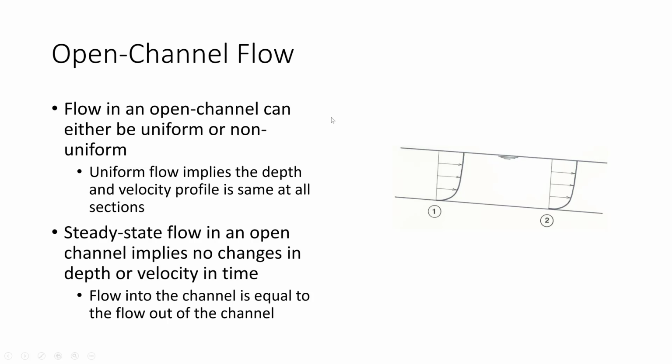Right. So understanding uniform flows and non-uniform flows in open channels is important. And again, if you look at the velocity profile, we have the bottom friction, which causes the no-slip boundary condition. So the velocity at the bottom is equal to zero, and then that velocity keeps increasing and is the maximum at the atmosphere-water interface, just because there is no resistance being offered to the flow at that point, because the air offers very little resistance compared to other flow lines of water inside that channel.